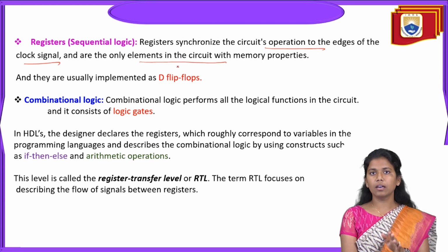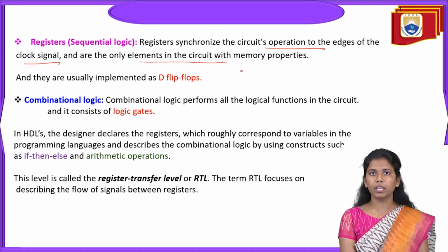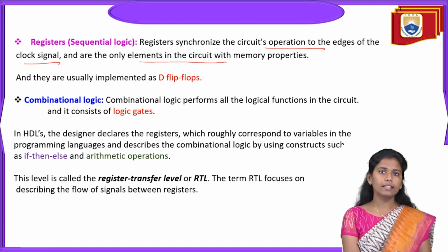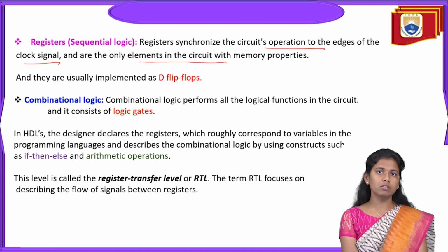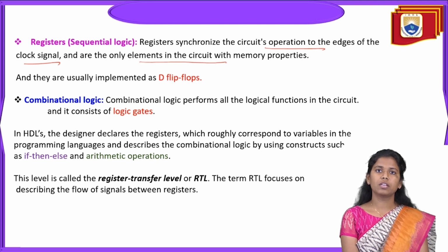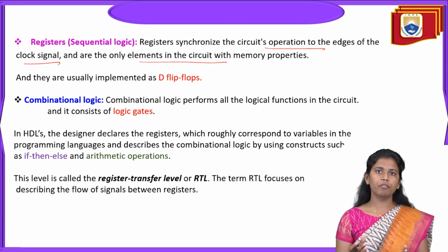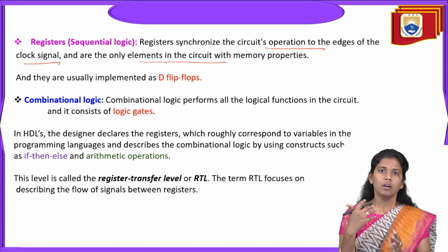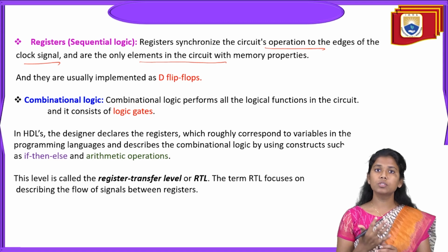So these memory elements just synchronize the circuit operation with respect to the clock signal. Certainly the clock signal is involved because we are using memory elements, right? Each and every flip-flop and latch uses the clock signal as well. Even registers are nothing but a group of flip-flops. When a group of flip-flops is considered together as one part, we say that it's a register. So in most areas, we are using the memory elements.